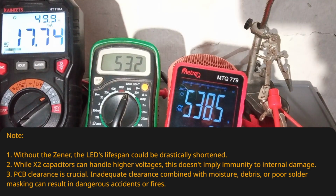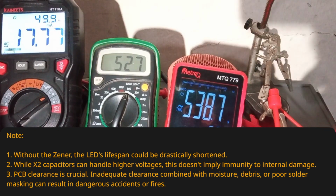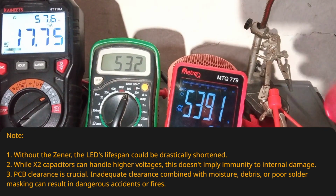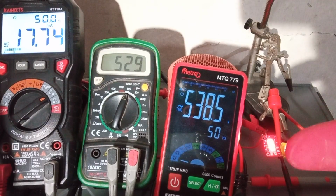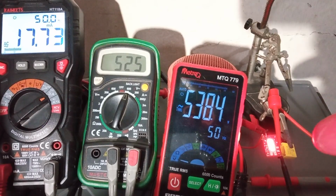So if I keep this turned on for maybe a few hours or even days, the capacitor will get slowly damaged, and because of the surges and high voltages, the holes inside the capacitor will get filled up by vaporizing the metallized layer from the other layers. So hope that makes sense, but we can actually cross the limit. Definitely this is not safe, this is actually damaging the capacitor, but it kind of works momentarily.